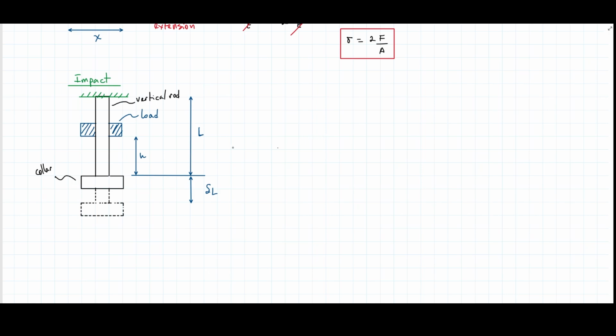So then let's see how is the stored energy, in this case strain energy. Let's bring a few relationships that we know. We know that strain, we already said it, equals stress divided by Young's modulus, according to the proportionality, because we're working within the proportionality limits. But strain can also be defined using these two terms here. Strain equals the deformation divided by the original length. Substituting one in another, the deformation I got from the impact depends on the stress, the original length, and the Young modulus. We know this relation, you have seen it before.